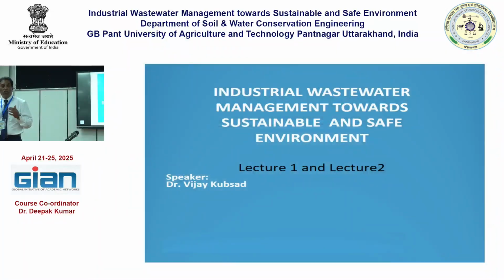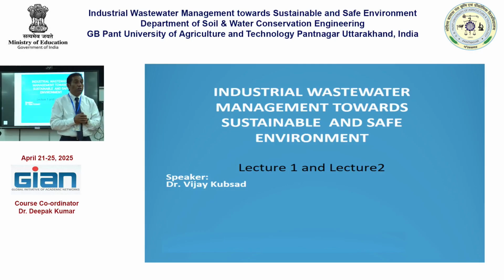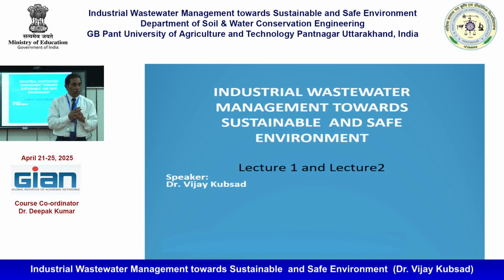And one particular lecture is on metals. Wastewater discharge consists of a lot of metals also. It depends upon the type of industry, but metals are equally important to take care of. Otherwise, that will mess up the whole treatment process. And even if it is in the sludge, it cannot be disposed. So that is one lecture and one tutorial I have covered, which you will find interesting.